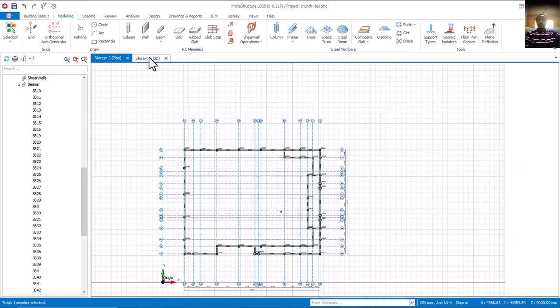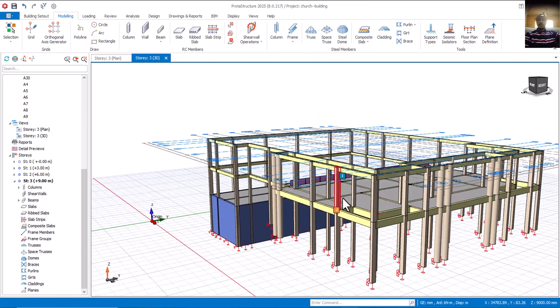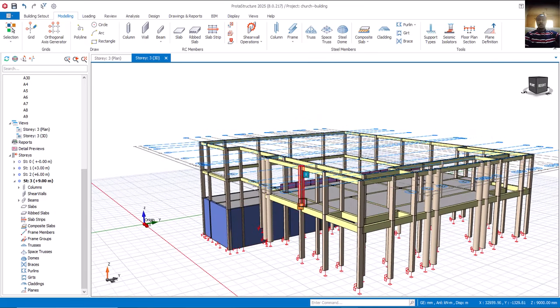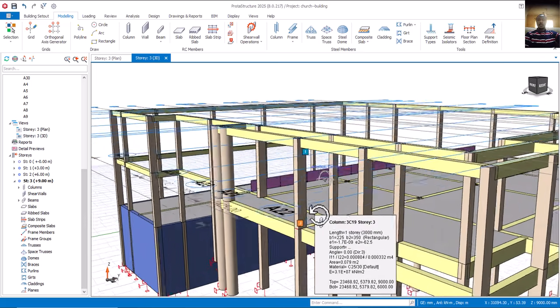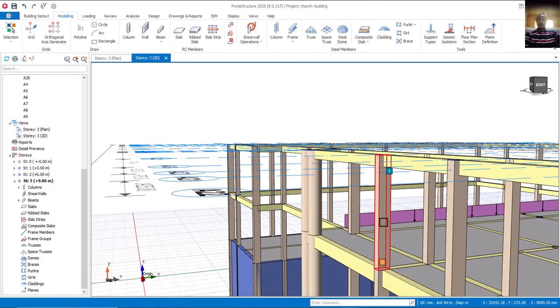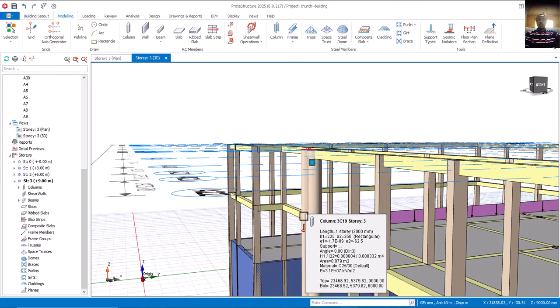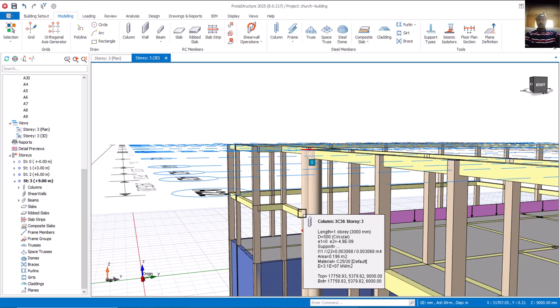So let's now check our 3D. Okay, we all have it now. So now we need to edit the height of our structure for this particular column at this level here. We can decide to reduce it from 230 to 225 by 225 instead of 225 by 350. All of this depends on your discussion with the architect.